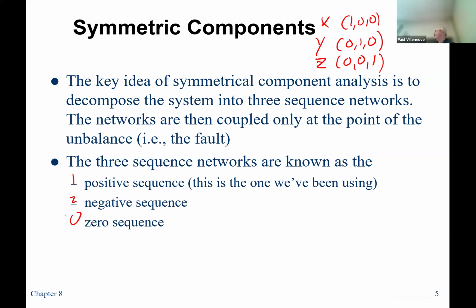0, 1, and 2. That's how we denote those. And that's common around industry. So if you were to open up a Schweitzer Engineering Labs relay manual, you would see how they would polarize on I or V2, which would tell that it polarizes on negative sequence voltage. It actually needs that voltage to be able to make a decision about stuff.